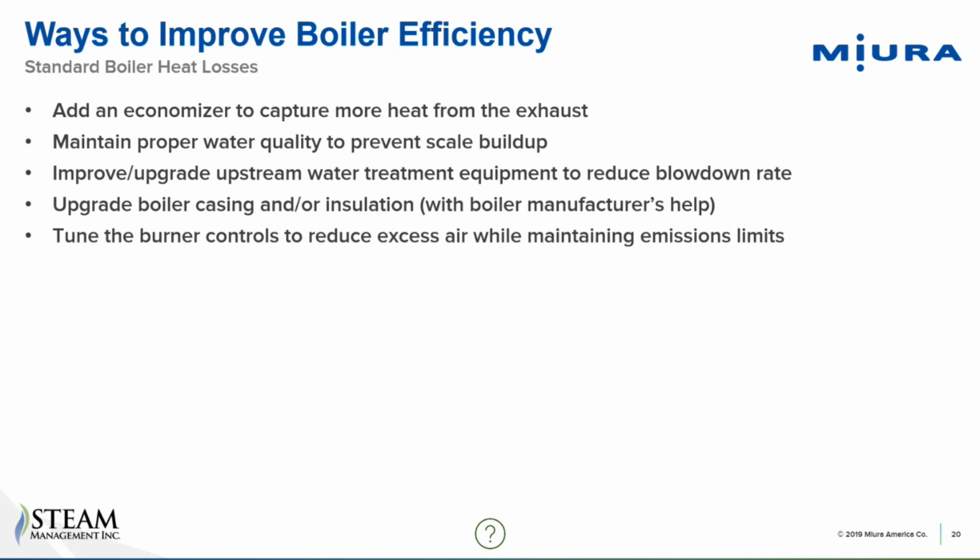You can maintain proper water quality. That's going to prevent scale buildup. Scale can reduce the effectiveness of your heat exchanger. So that's very important. That's going to, over time, gradually decrease the efficiency of your boiler.